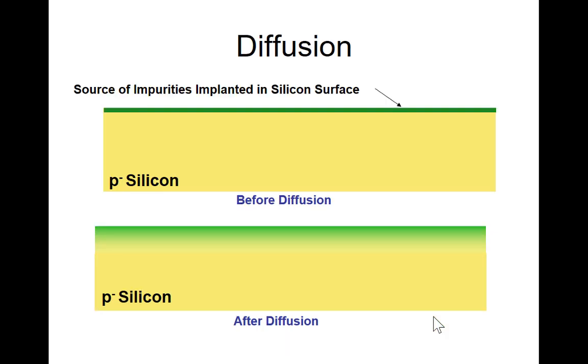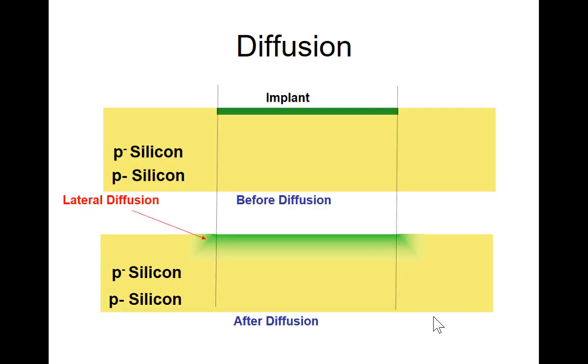And similarly for implantation, if you implanted some materials on the top, and then after your diffusion, it can go down. With implantation, you can have a controlled small area, whereas deposition is typically used for larger areas. With implantation you can control where you implant, so you implant just that part, and then you let it diffuse, and you end up forming a shape that is almost like a